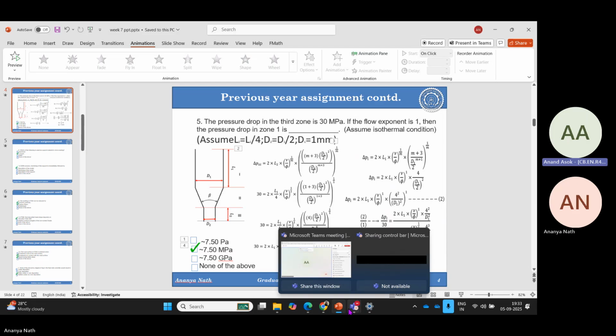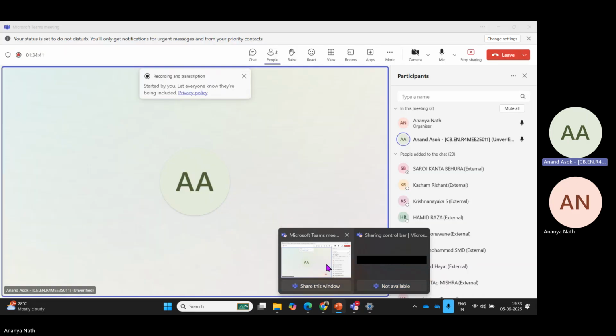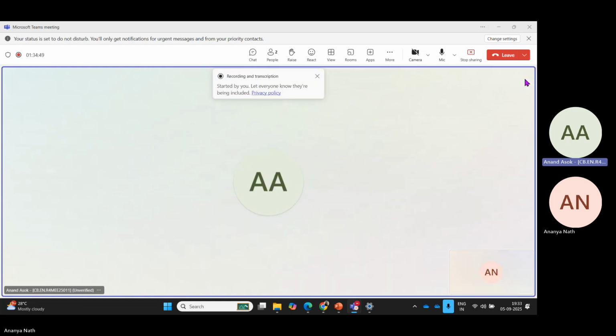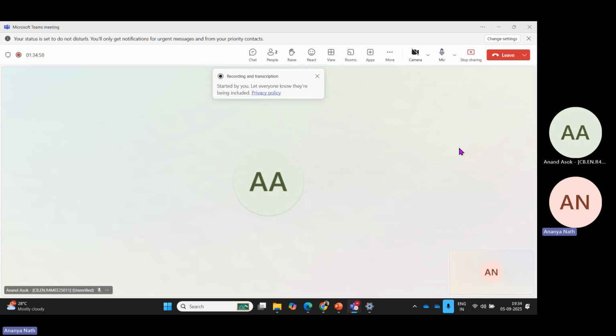Yeah, because to get the continuous beam, if we increase the distance from the liquefier to the material that is deposited, then the velocity will decrease. Yes. To get the same bead, because when you are moving up the nozzle, you're increasing the standoff distance.